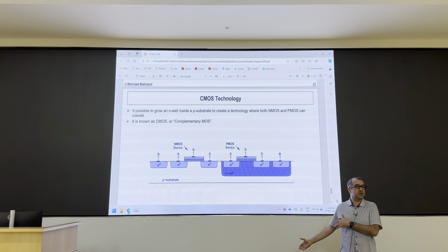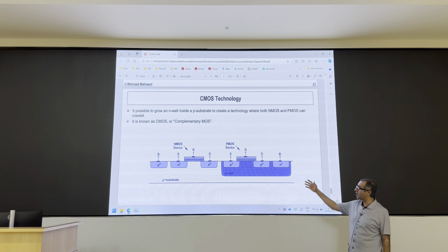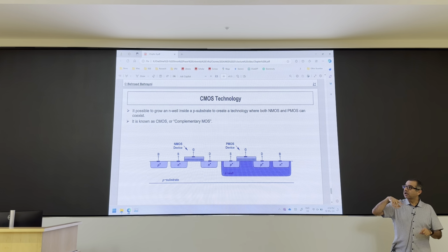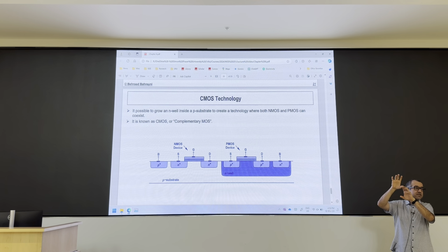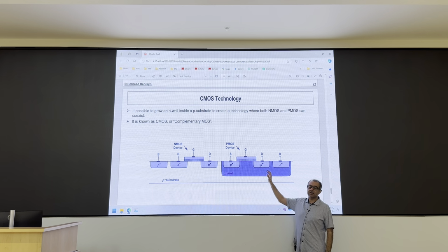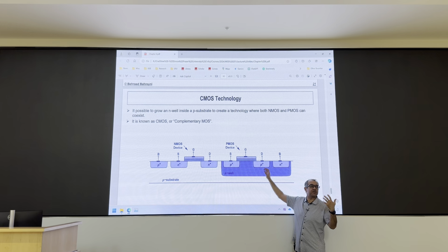Extremely important for digital stuff, because transistors are the smallest things you can make, and digital electronics need a lot of transistors. So if you want to have gates and everything else, you need both P-type devices and N-type devices, and you need to find a way to make them side by side. You can do the job of, let's say, a PMOS with a resistor, and then still make your gate. You make gates with diodes and resistors. You can make a gate with a resistor and a transistor, a BJT. You can do the same thing with a MOSFET, but your circuit will be